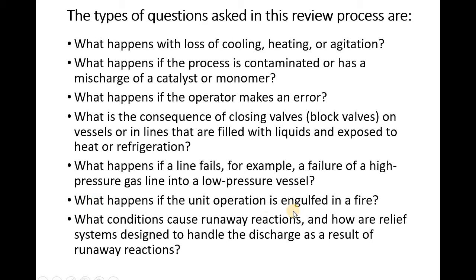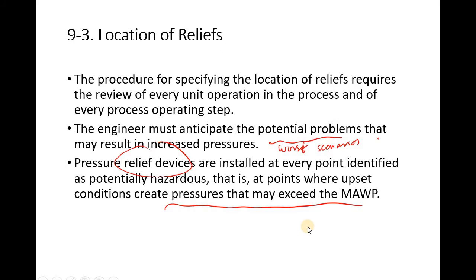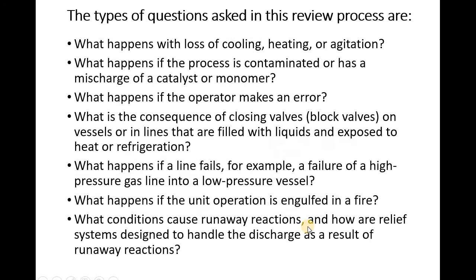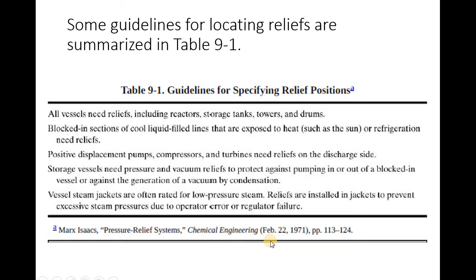What happens if the unit operation is engulfed in a fire? If there is fire, that means you have vapors, you have pressure, right? What conditions cause runaway reactions? You have a runaway reaction, you cannot catch it. It's running and it's just producing more and more heat and of course pressure. So how are relief systems designed to handle all this?